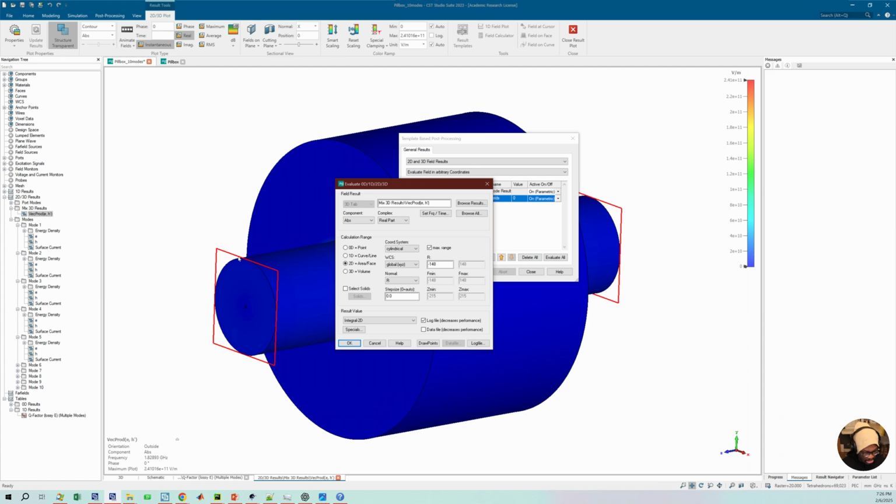I did not check that. I just changed it to cylindrical coordinates so that I am sure that what I'm considering is just this face and not the entire plane containing the face. So I would go to cylindrical coordinates, and I want the normal to be Z, so I want this plane, and then I want this to be at this face, which I think was LBP minus L cavity divided by 2. I think that was it.